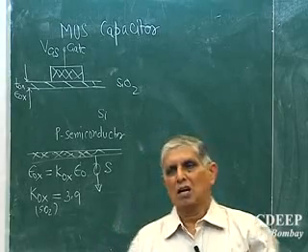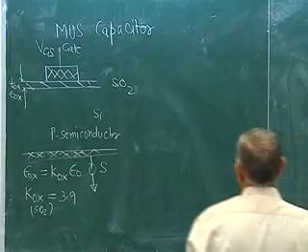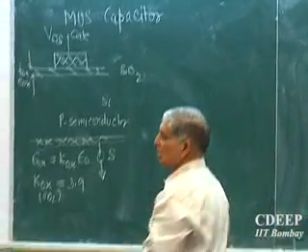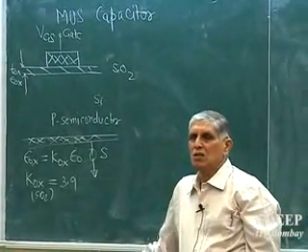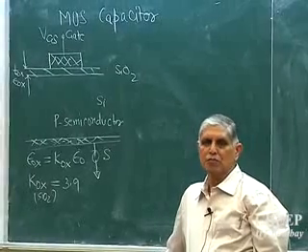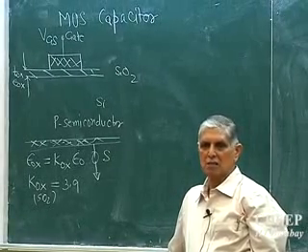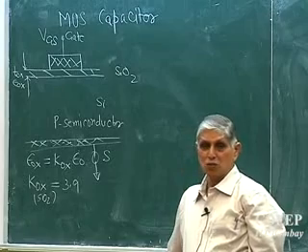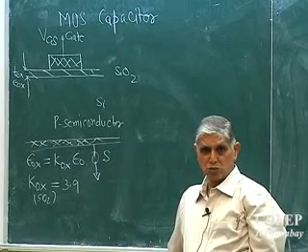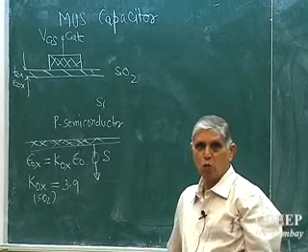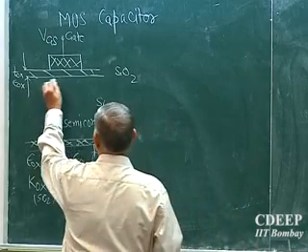And yesterday we discussed that depending on the polarity of VGS, there will be three states of situation in the MOS capacitor. If VGS is negative, the gate is negative with reference to the bulk, then we say holes will start accumulating.